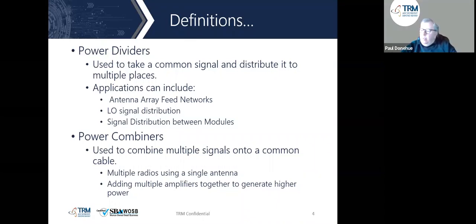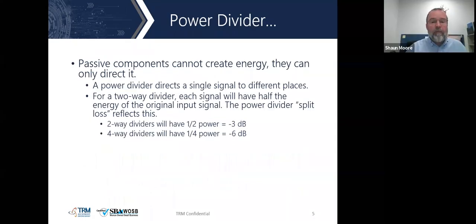I've also heard people refer to power dividers as being passive. What exactly does that mean, Shaun? Yeah, sure. So a passive component means that we don't have to plug it in to a power source. What that means at a bigger level is that the signal that drives the unit also powers the unit, which means there is no additional power source there.